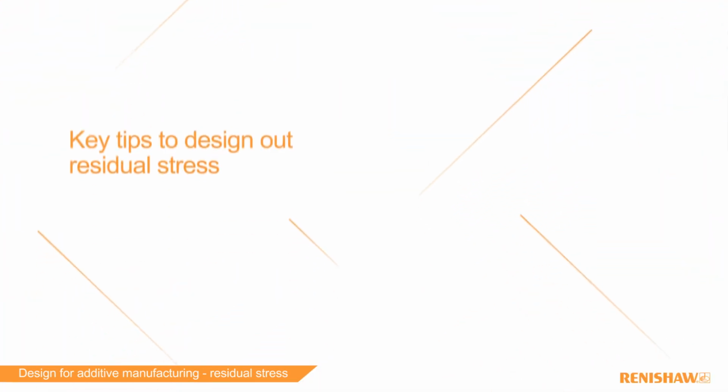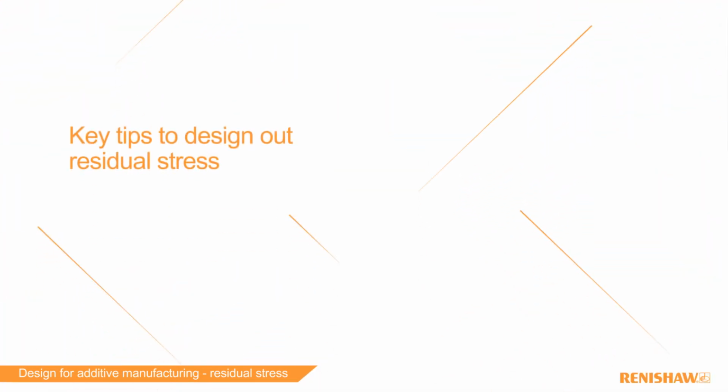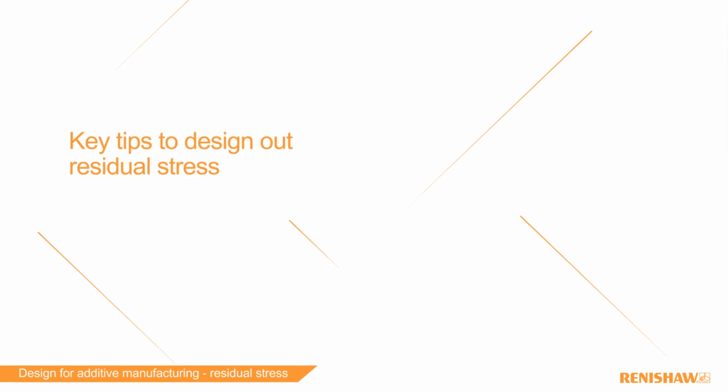Heating of the build plate is another technique used to reduce residual stresses, whilst post-process heat treatments can also relieve the residual stresses that have built up. My key tips to design out residual stress include: avoid large areas of uninterrupted melt, be careful about changes in cross-section, use thicker build plates where stresses are likely to be high, and select an appropriate scan strategy.